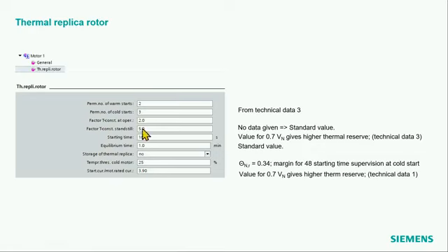That means if you then start up this motor 3 times from cold state within normal voltage, then you will not reach the limit 1 temperature maximum limit, because it's a faster startup with less stress for the rotor. So you have more margin, more leeway for the starting up of the motor. And you can do this if the motor manufacturer states you that you have also these 3 and 2 starts, number of starts for the reduced voltage, for example.